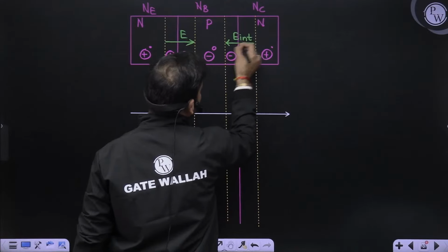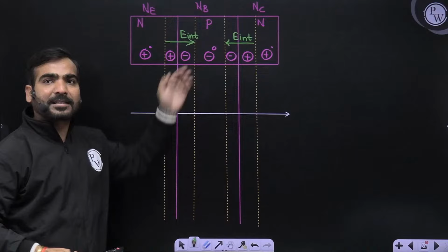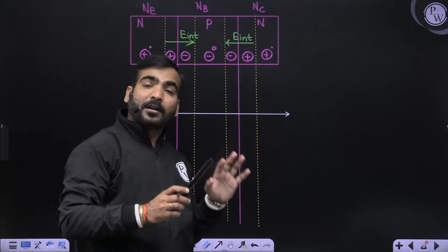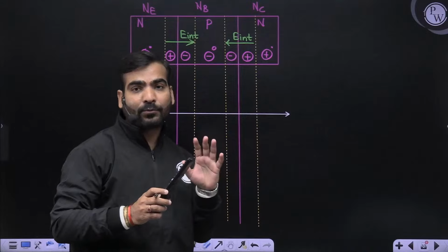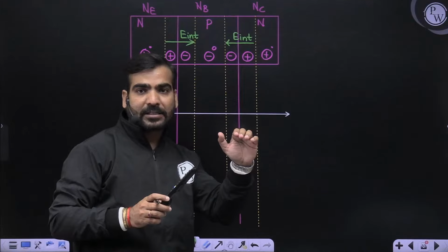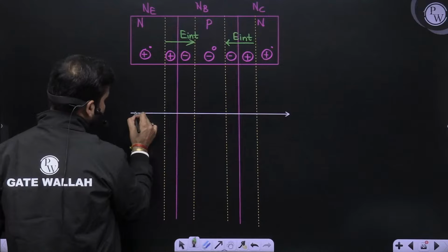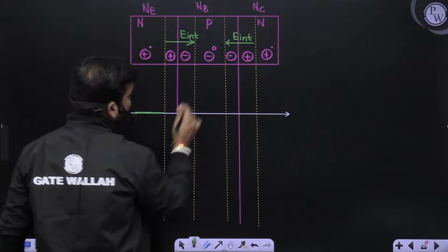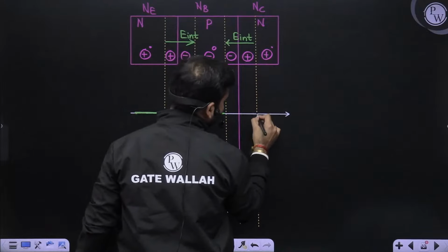From positive charge to negative charge. Here the electric field is going in plus X, and since the diode has abrupt doping, meaning constant charge density, the electric field is linear. Outside the depletion region, in the neutral regions, the electric field is 0.